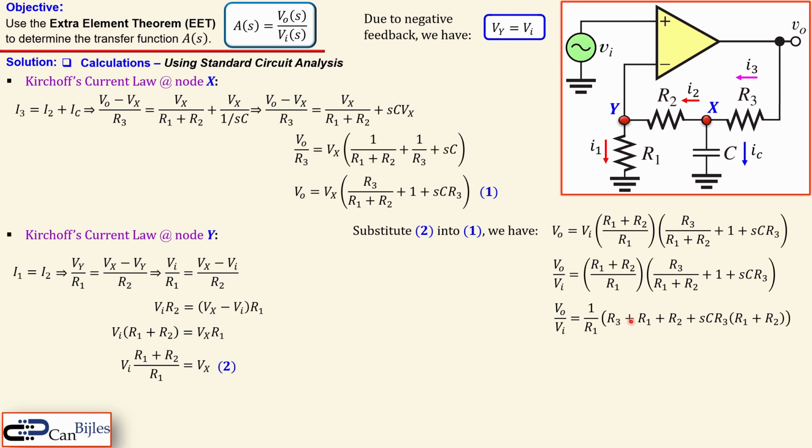What we also see is that this is a summation of 3 terms that can also be taken outside. I can do that by dividing out this complete expression by the summation of these 3 resistors. This is actually the next step. And this is done in order to see the time constant, so the zero frequency, much more clearly. You don't have to do that, but it is more convenient.